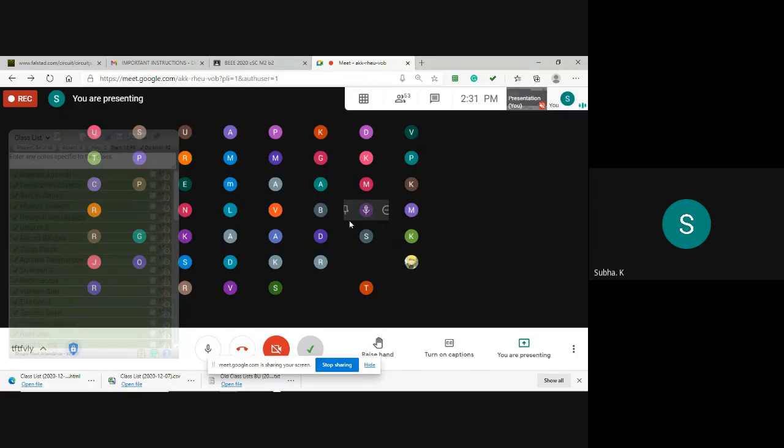You have to use a Karnaugh map and simplify that expression and implement it with logic gates. That logic gate implementation, you have to do it in each circuit. You have to obtain the output, the same way as I proceeded today. That is the next experiment.